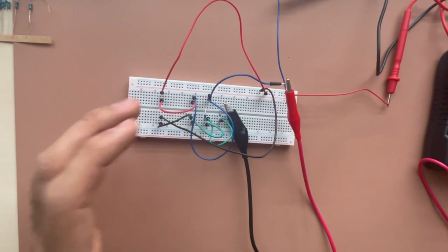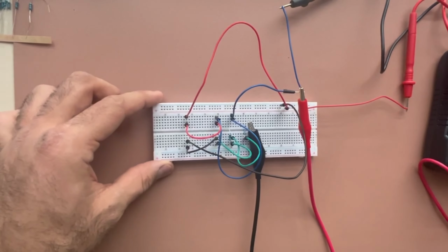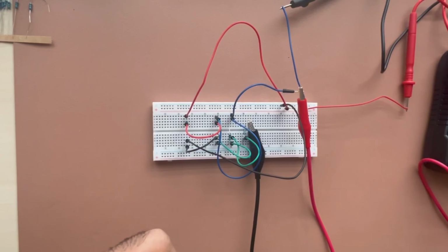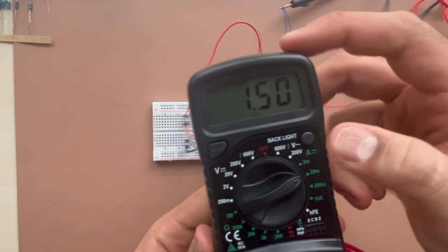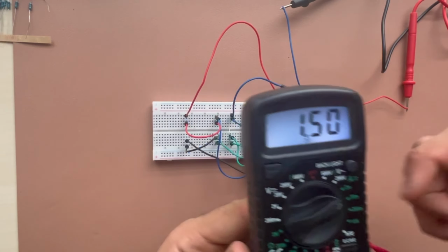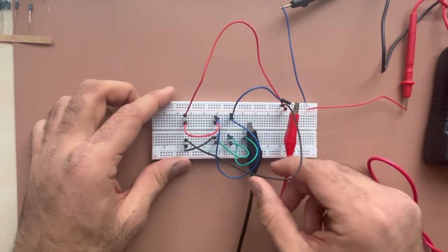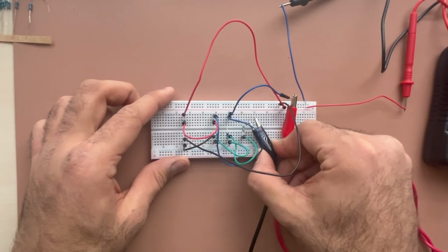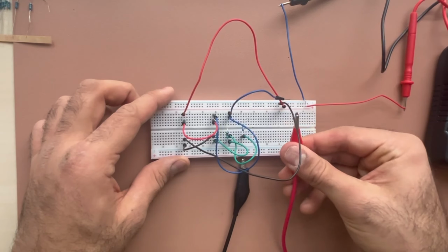The only thing I have to do is just turn the source on. So if you turn it on, based on the calculation and based on the voltage or other ways that you have in your mind, it should be something around 1.5 milliamp. So you can see over here, if I turn it on, I do have exactly 1.5 milliamp. So it means that the current that goes through the final one, the 10K, is right.